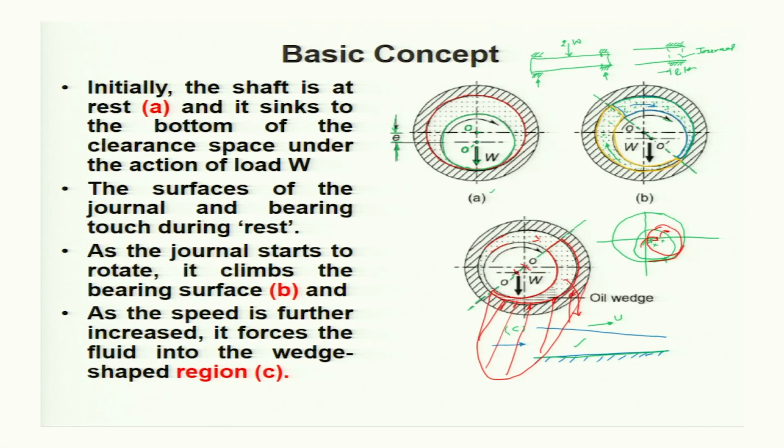This pressure will lift the journal, and there will be liquid between the journal and the bearing, and this journal is rotating in a clockwise direction.